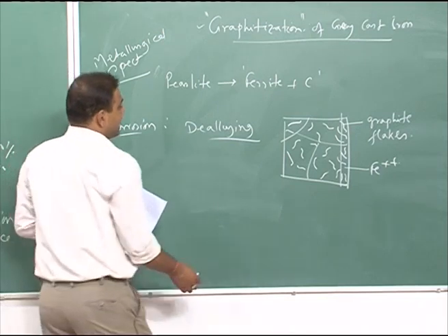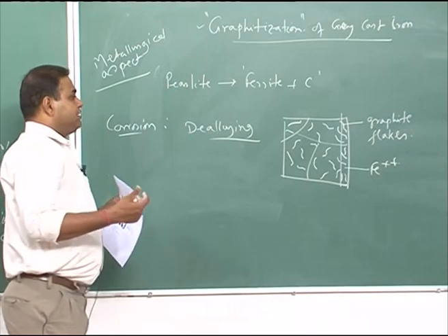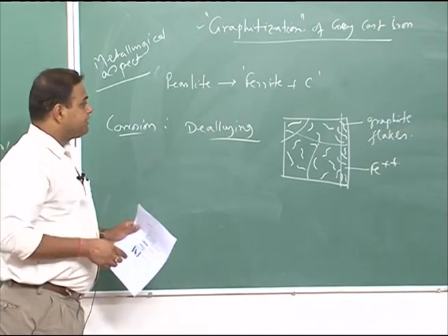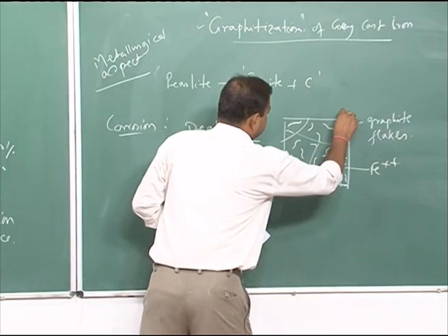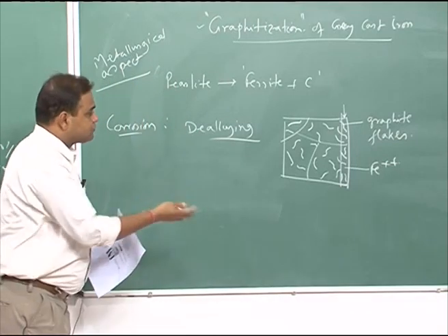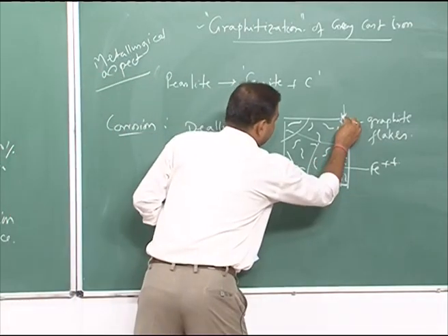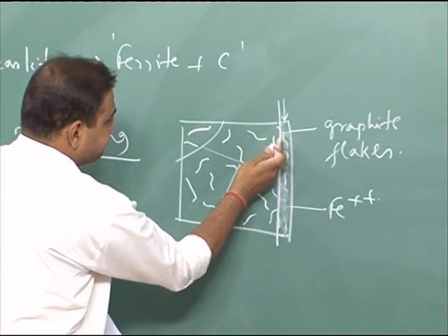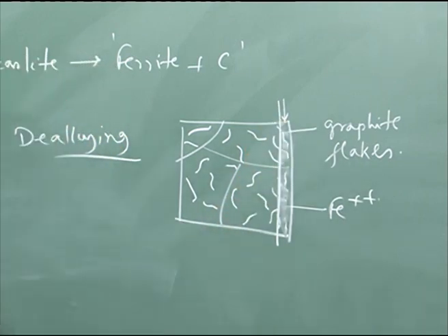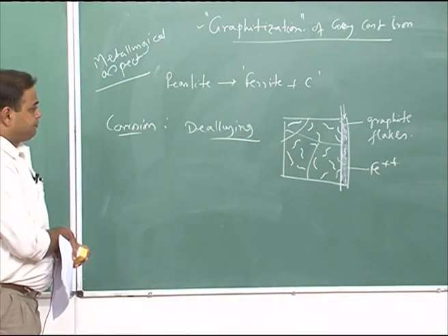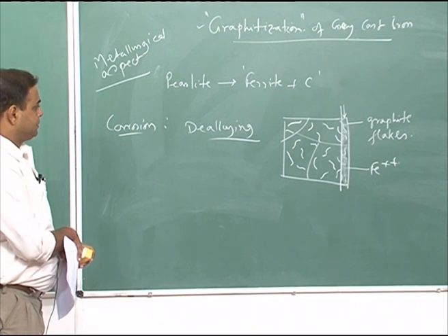Now, this does not happen if the corrosive nature of the solution is very aggressive. Then the corrosion is so fast that the network does not form, it goes out. You have almost uniform corrosion, and the surface always remains the base metal surface, and this part goes off in case of a highly corrosive solution.